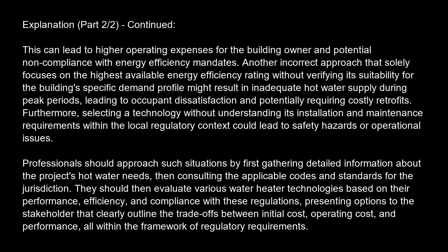Another incorrect approach that solely focuses on the highest available energy efficiency rating without verifying its suitability for the building's specific demand profile might result in inadequate hot water supply during peak periods, leading to occupant dissatisfaction and potentially requiring costly retrofits. Furthermore, selecting a technology without understanding its installation and maintenance requirements within the local regulatory context could lead to safety hazards or operational issues.